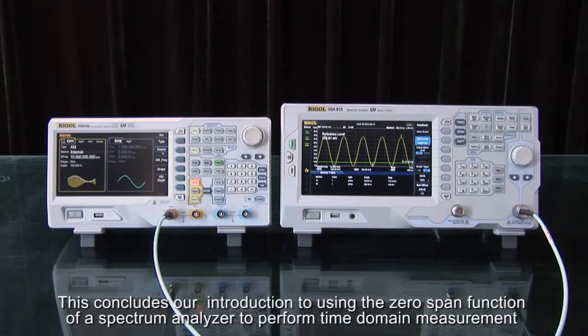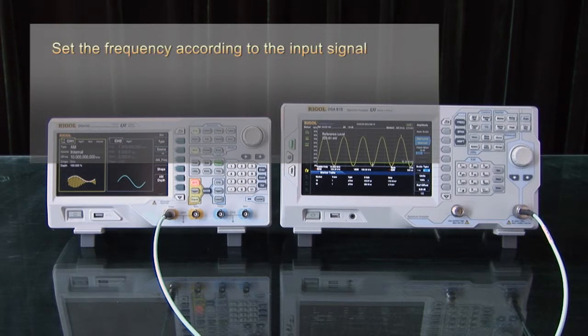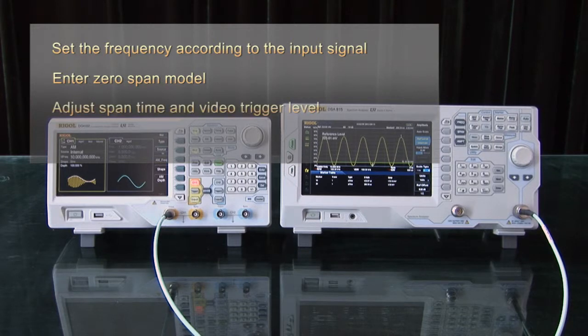This concludes our introduction to using the zero span function of a spectrum analyzer to perform time domain measurements. Here are some notes. Set the frequency according to the input signal. Enter zero span mode. Adjust the span time and video trigger level, and then use marker functions to perform the measurement. Thank you.